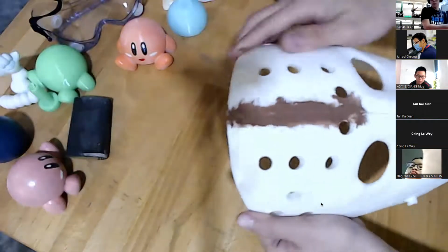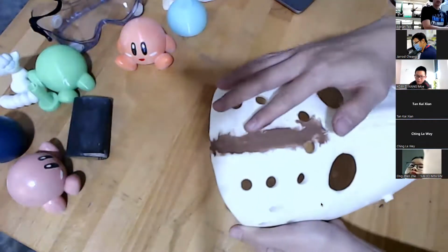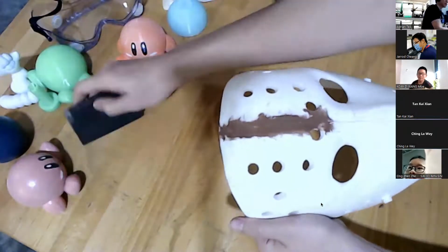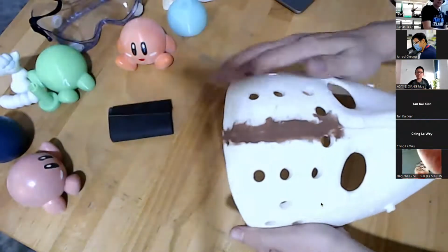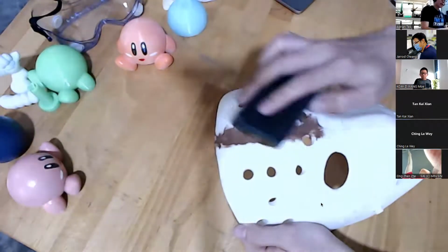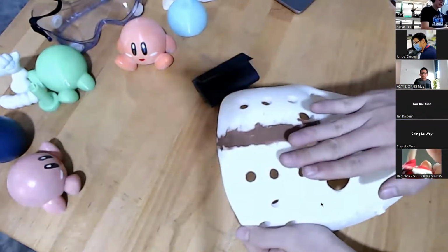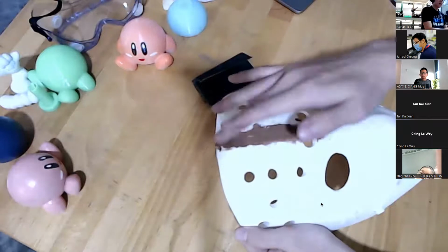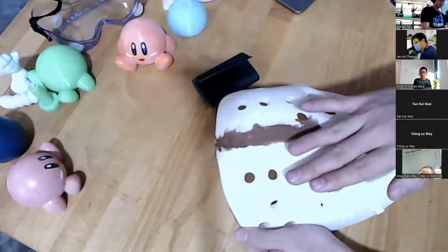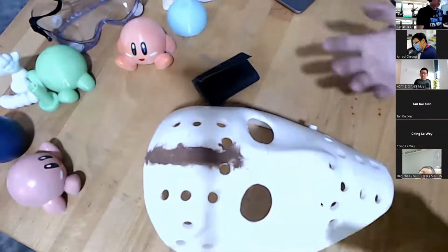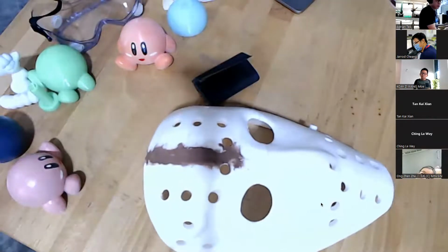So the next step is you leave it to dry. You have to let it dry first. Don't sand it immediately because it's gonna remove all the filler. Let it dry for a while, and after you finish drying, you sand it, flatten it, make sure that it's the same level with your print. Right now you're filling the hole. That's why it's called filler. You're filling the line over there. After you're done, you sand it down, and then we continue with priming, right? So this will remove holes.